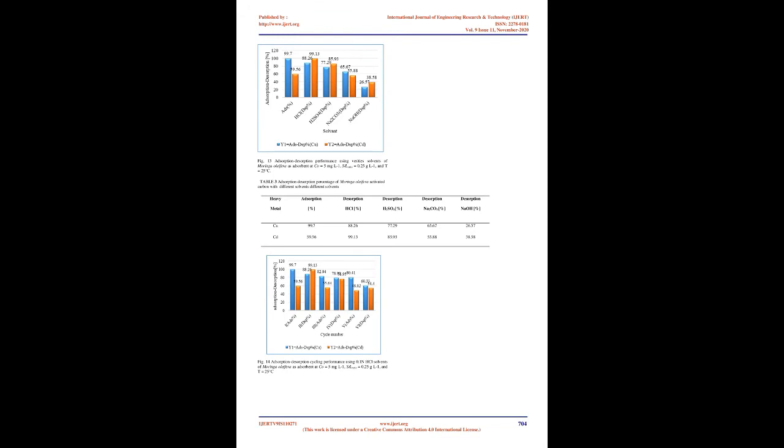H. Effect of pH. The adsorption performance of activated carbon can be affected by the pH of the solution. [46] In this study, the removal percentage of both metals was measured over a solution pH range of 2 to 12, as shown in Figure 12. The graph shows that with increasing pH values, the metal removal percentage also increased, and at pH 11 the maximum removal percentage was obtained.